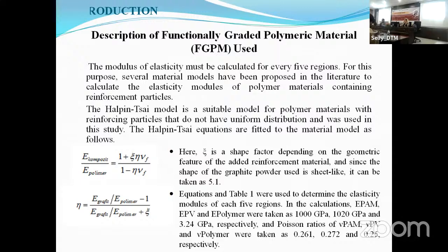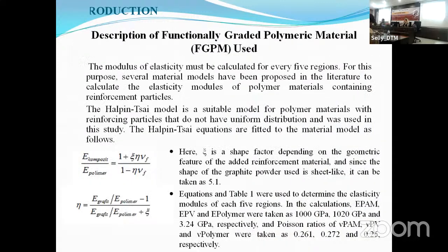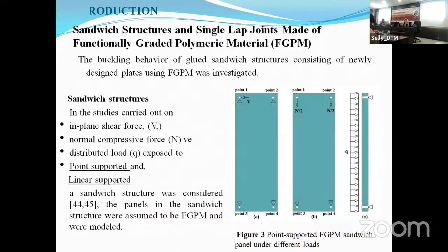Anyway, we can get considerations of some mechanical properties. If you use ANSYS, it asks you to please define the material. The basic option, of course, is a linear, homogeneous, linear elastic material, but that is too basic. So we need some options, we need to create them by using the ANSYS API program or MATLAB.